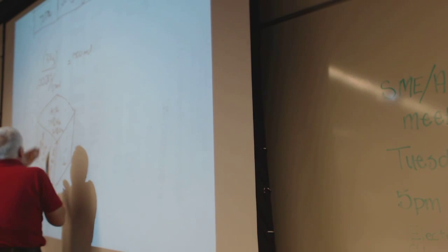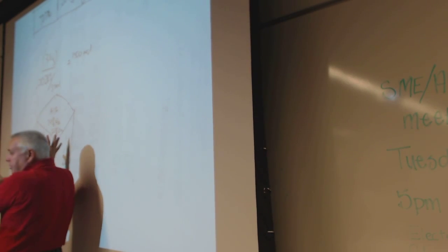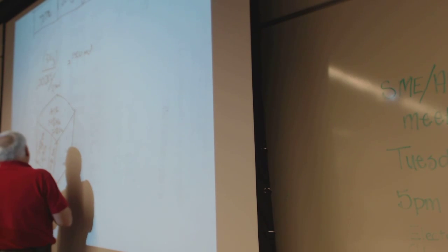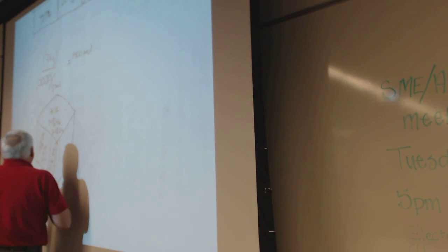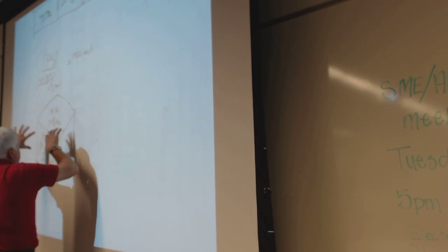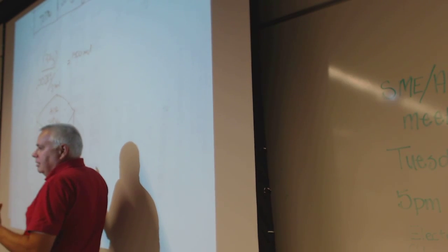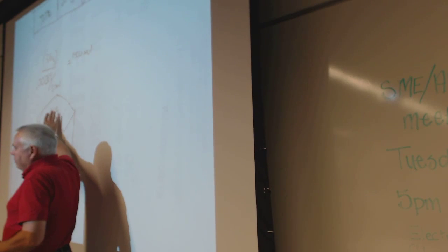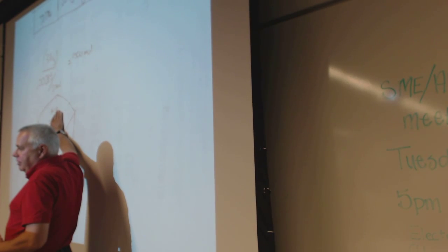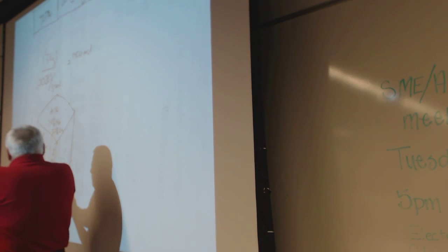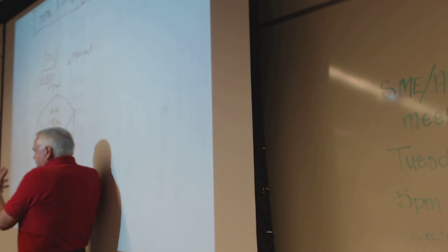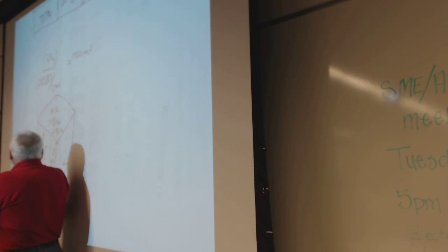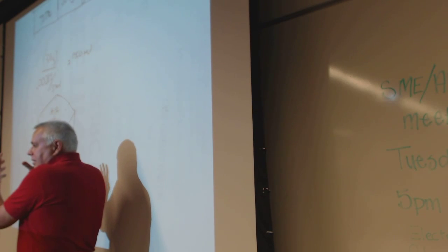And now, magically, I'm going to cut that box. This was 1 cubic meter to start with. Now I've got 0.21, or 21 liters, essentially, is oxygen, and 79 is nitrogen. I can cut that box and take it into 2 boxes, and it's all these magic boxes. If this was at 100 kilopascals, standard atmospheric pressure, to start with, now I've got a box that's 790 liters, 1,000 liters to a cubic meter. 79% of the cubic meter is nitrogen at atmospheric pressure.